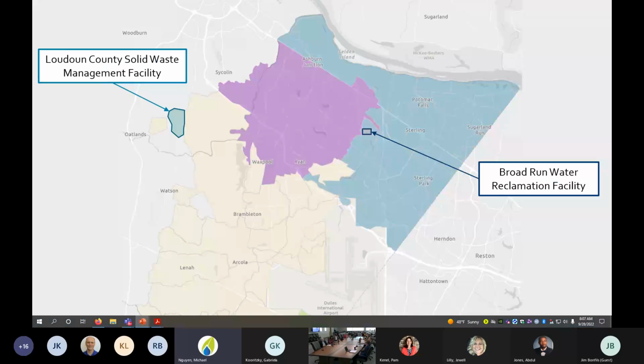Just curious, with the process of going from point source to wastewater treatment and the biosolids, is that a sequential process in terms of removing PFAS? Or do you see the wastewater treatment and biosolids occurring concurrently? They occur concurrently because as you treat that liquid, you're generating the solids. So you need to do both of those together. So really you're looking at a cost benefit analysis on the point source and seeing what the PFAS levels are then, and then evaluating after you've done the other two. Yep. And that point source reduction will affect both of those other systems. Okay.